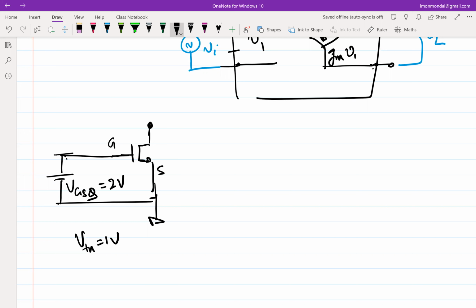Why? Anybody can volunteer? There is charge, like a capacitor, there is charge here, right? Because it's above threshold voltage. I have applied a VG which is above threshold voltage. But charge needs a path to flow; when current flows, you have a current. But whether it's on or off, does it depend on whether you have a current or not?